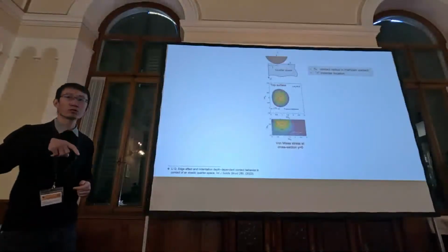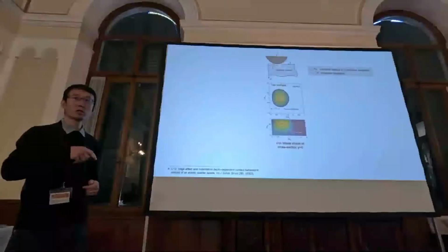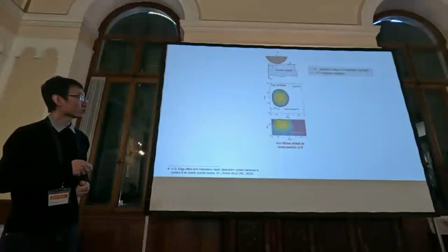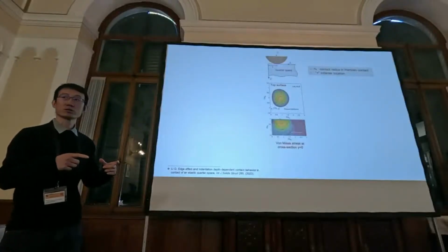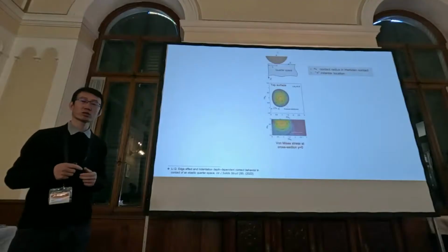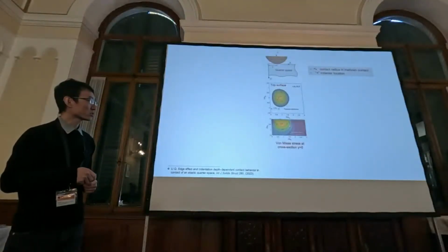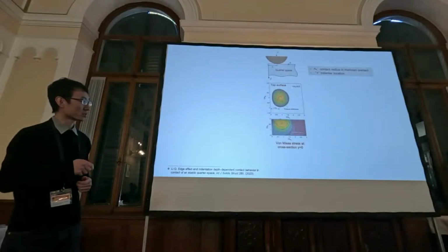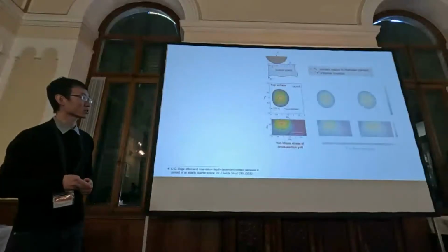This is the top view of the contact area, and also the pressure distribution on the contact area. So we can see the contact shape. The shape of the contact area is not circular, and the Hertz stress at the cross section of this part is not the classic Hertzian contact.